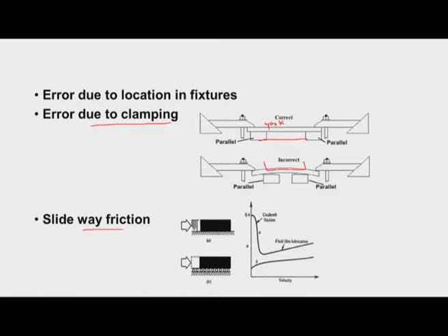Also, because of the slideway friction, the movement of the tool will not be proper; there will be jerky motion. Because of that, the surface finish may get affected, or sometimes the geometry is affected.